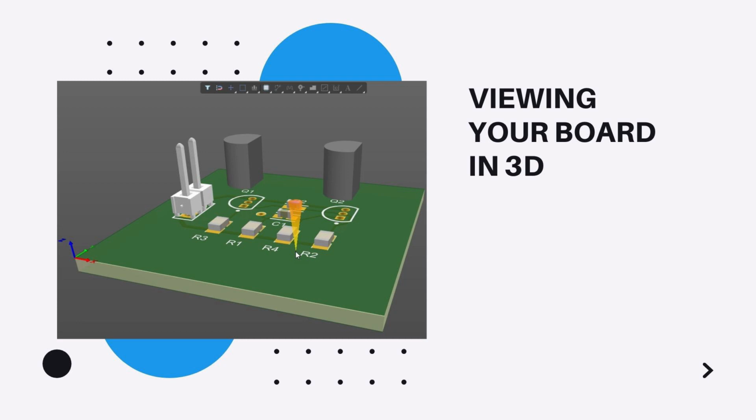The 3D display colors can use realistic or by layer, which are the layer colors defined by the 2D layout mode. There are a number of 3D configurations defined. Explore this in the General Settings of the View Options tab of the View Configuration panel. For example, the Altium 3D DK Green configuration is applied on the image shown in the previous tutorial. There are controls to configure the layer colors as well as the board thickness in vertical scaling, which is actually handy for examining the internal layers and interconnect structures in the PCB.